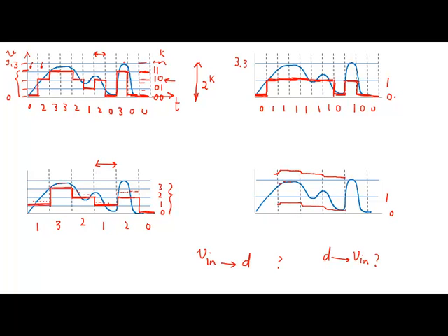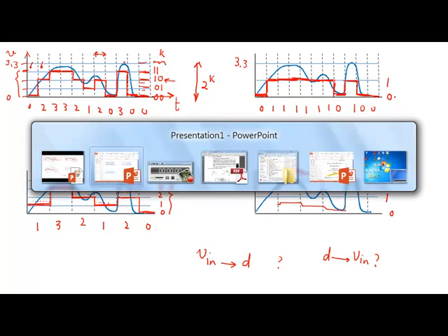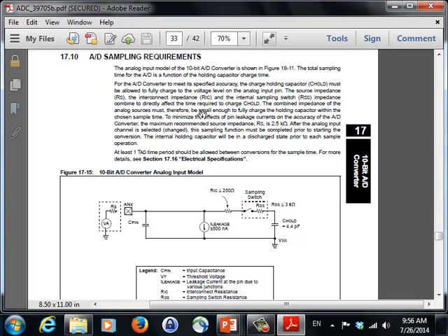And once you do the sampling, then there is the actual conversion. There has to be some process that says, let's take the voltage on this capacitor, and let's try to approximate what value it falls onto among these levels that you have, and convert it to the digital, right? And that's called the A to D conversion time. In the PIC, you're going to look at both of these values, and we can take a look at the manual and see what these values are.